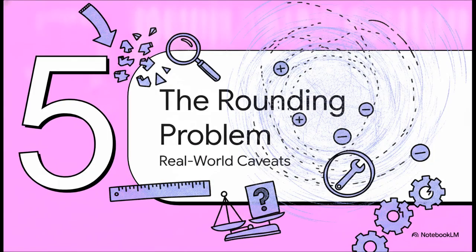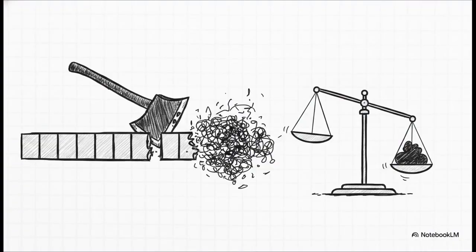Finally, Section 5, the rounding problem, the messy real-world caveats. The absolute simplest way to drop fractional bits is truncation. Just chopping them off. But chopping has some pretty severe flaws. Because of how 2's complement works, chopping always reduces the value of the number. It generates errors ranging from 0 to almost 1. And worst of all, it creates a biased, asymmetrical approximation because the error range isn't symmetrical around 0. Over millions of calculations, this bias will drastically skew your final results.